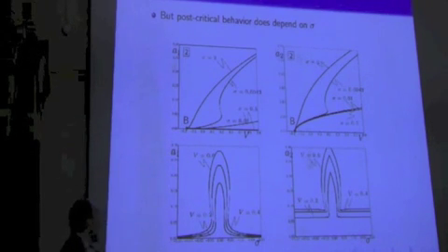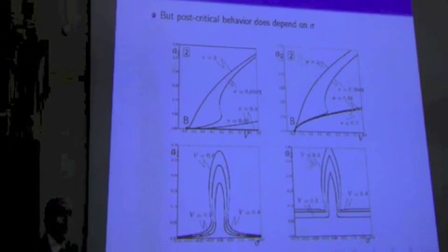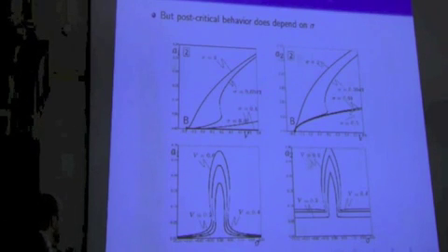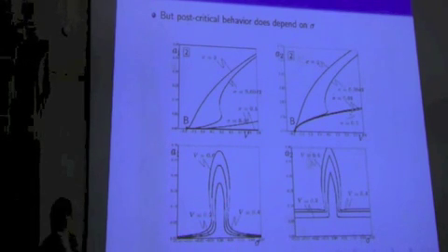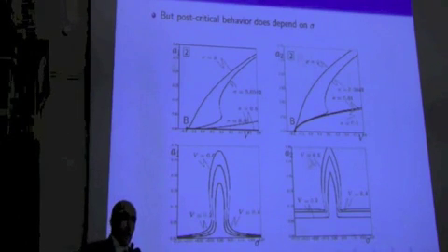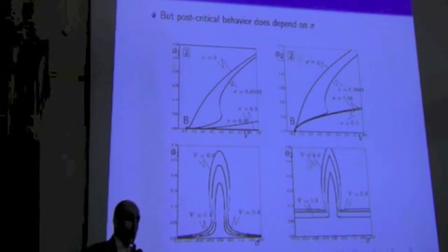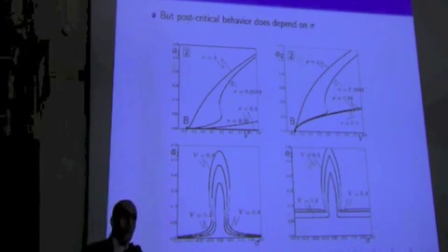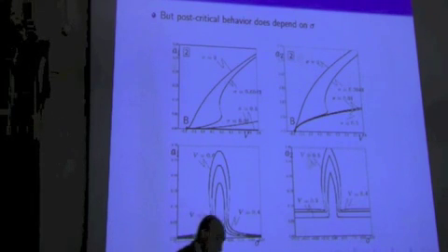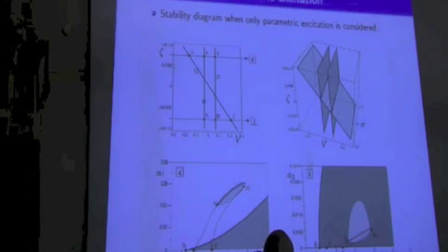we found in another work in case of non-resonant double Hopf bifurcations. It is an important result. It means that, of course, it happens both if we increase or decrease internal detuning. It means that although there is an ordering violation, the equations describing the internal resonance double Hopf bifurcation continuously can describe the case of non-resonant double Hopf bifurcation.